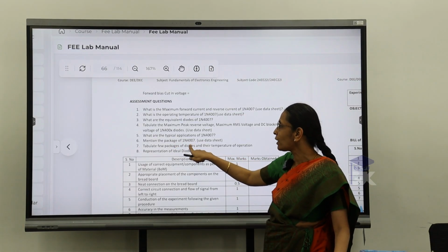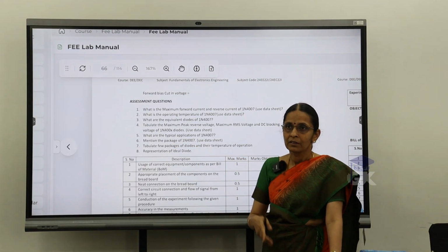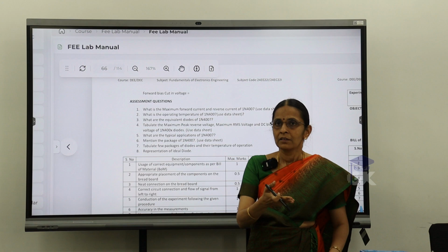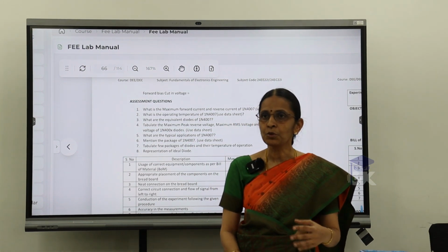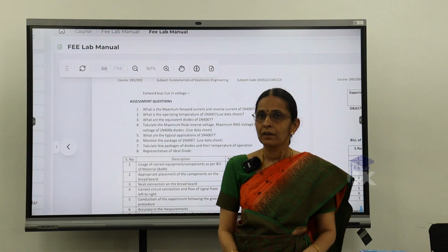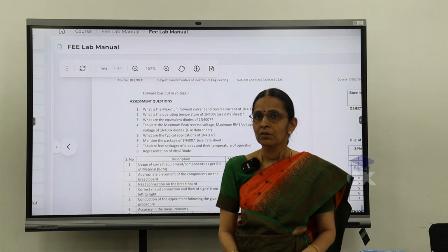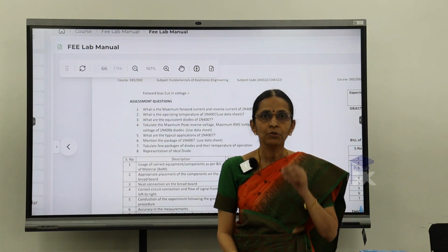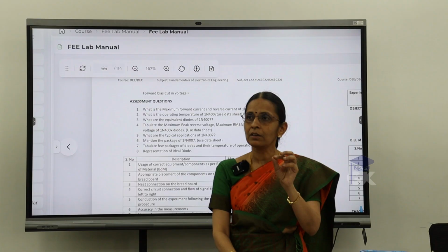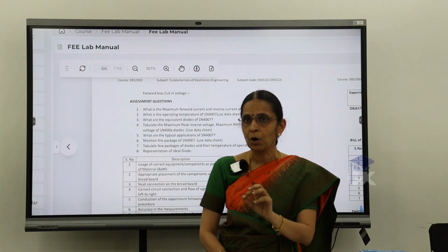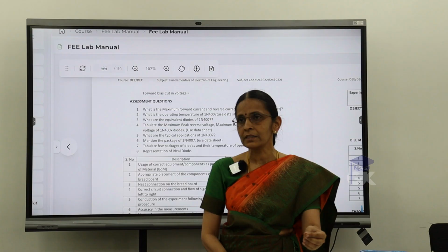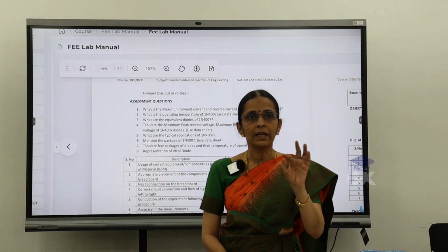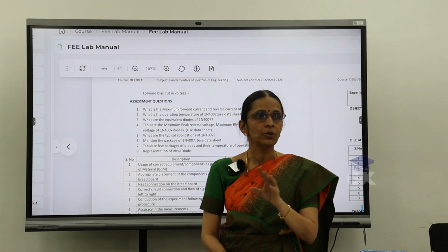Next, mention the package of 1N4007. I think you have done this course given by Shanbag sir. Did he introduce you to the packaging? Yes or no? Yes. So if you say the diodes, they have got a DO. DO means diode outline package. And if it is a surface mount device, SMD. Okay. So there is a number. Say I have DO35.